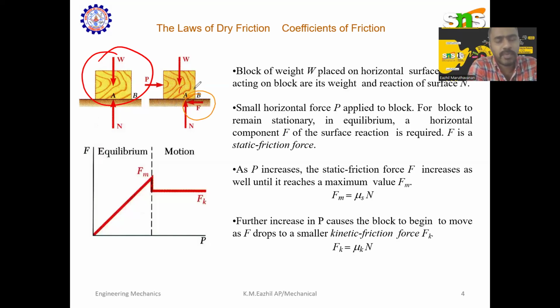Here is the applied force; the frictional force will be in the opposite direction. The self weight of the block acts perpendicular to the ground plane, and the normal reaction force acts perpendicular to the lying plane, opposing the weight of the block. This is what is given in the diagram, and it will be in equilibrium conditions.